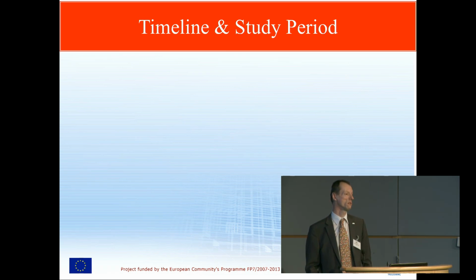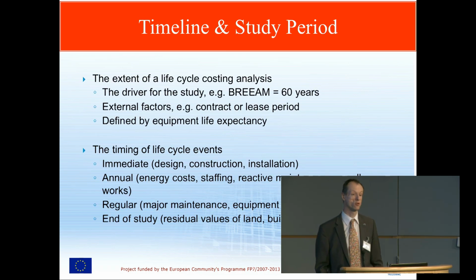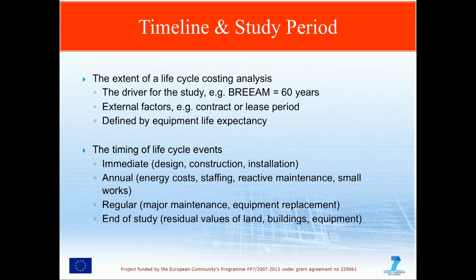Sometimes the life cycle is determined by the driver which is behind the analysis in the first place. So for example, if you are carrying out a BREEAM assessment, the Building Research Establishment Environmental Assessment Method, and you want to get the credits for doing life cycle costing, then they stipulate that you will need to do your analysis over a period of 60 years. That may or may not have anything to do with the project that you're actually concerned with, but tough. That's what they say, so that's what you've got to do if you want to get the credits.